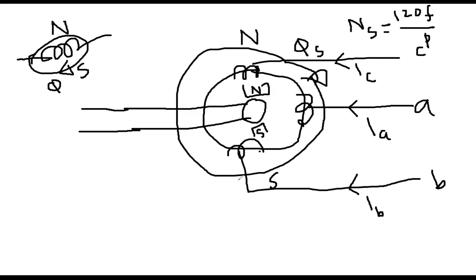You look, this North Pole and South Pole is moving. So because this North Pole and South Pole is moving, what will happen? This physical pole is static in position initially. So when this North Pole is aligned, you see in that fashion, what is the reaction of North and North Pole? Is it attraction or repulsion? It will be repulsion. So when this rotating North Pole is perfectly aligned with the North Pole, then like it will repel. This is moving in this direction, but this physical pole will be repelled a little bit in the other direction.